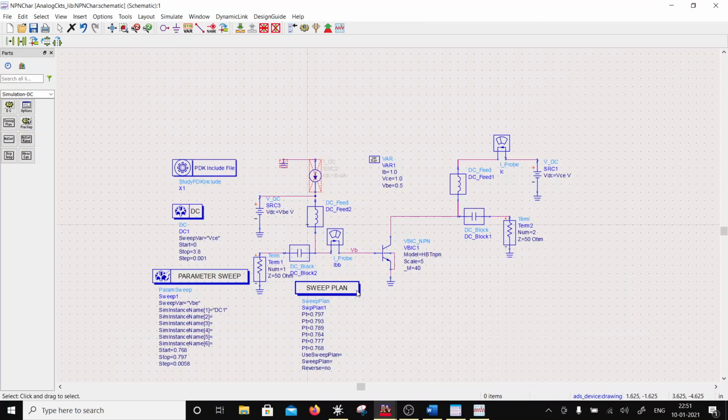And why is that? The reason is the base width modulation. If you are purely varying the collector-base voltage, the base width modulation is going to be more in case you bias with a voltage, because any change in VCE is a change in VCB, since VBE is held constant.